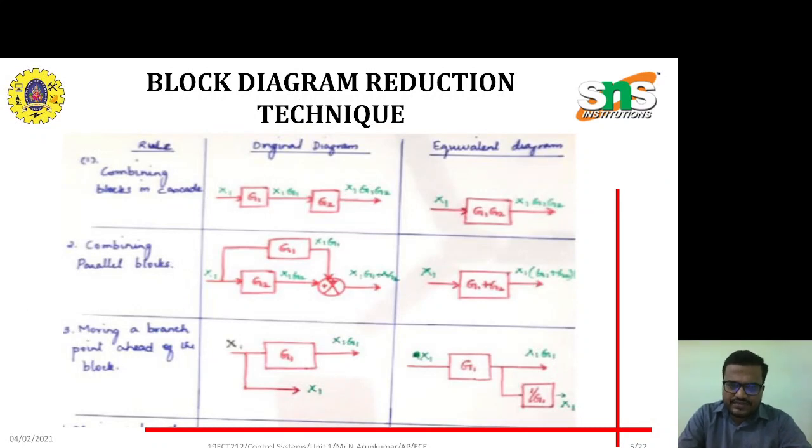In this case, we are going to see how block diagrams are reduced by using these reduction techniques, and some properties of the block diagram reduction techniques. Initially, we combine the blocks G1 into G2. If we consider two blocks in series, we can combine them by multiplication, G1 into G2, so that we can take it as only one block in the equivalent diagram.